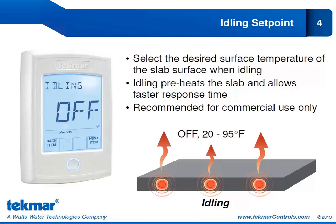In the Set Temp menu, you will enter the desired surface temperature of the slab when idling. Now we have quite the range here. You can turn idling off, which is actually the default position, or you can configure the idling set point to be somewhere between 20 and 95 degrees. Typically, an idling set point would be mid-20s. It could be high 20s in critical safety areas.